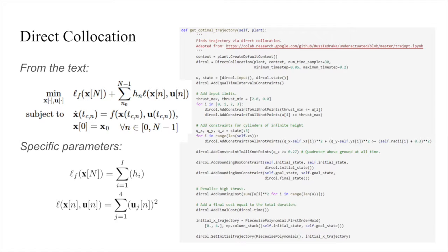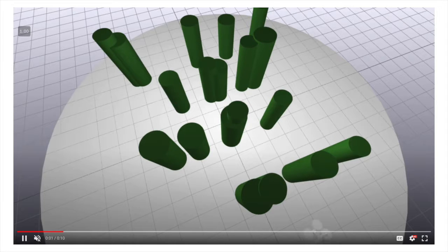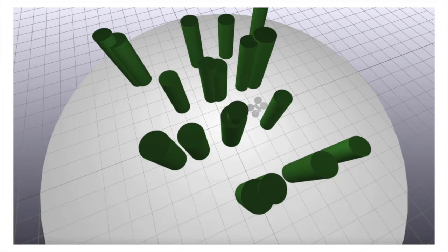The square of the rotor thrust values were used to take into account the relatively linear relationship between thrust and rotor speed, and the nonlinear relationship between rotor speed and power consumption. The output of this algorithm tends to appear ideal. The quadrotor does not make sharp turns, fly too fast, or waste energy ascending or descending. However, this algorithm requires prior ground truth knowledge of the map, which would be very difficult to determine outside of the simulation. This is why we moved on to our second technique.